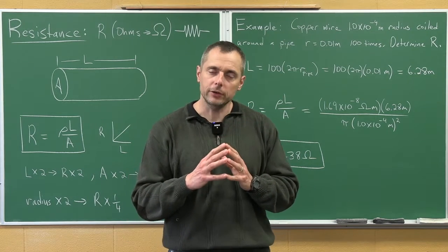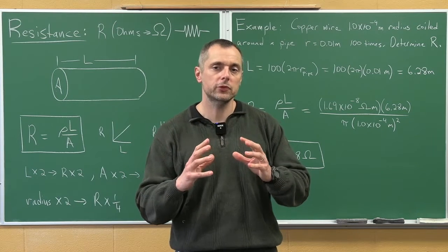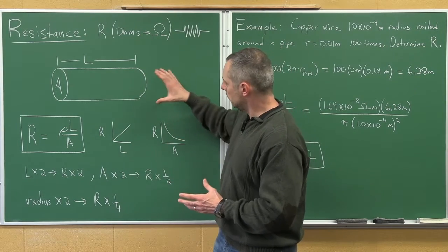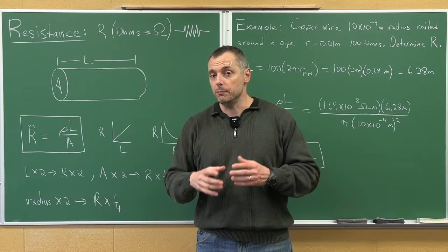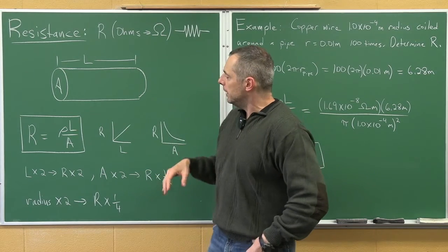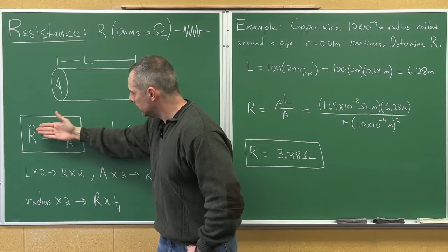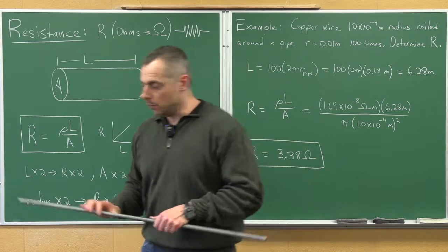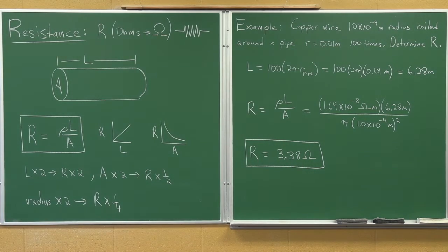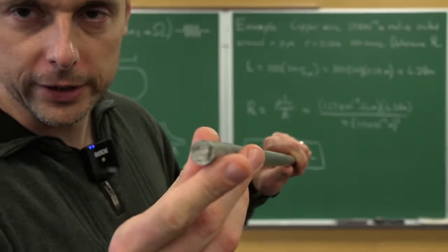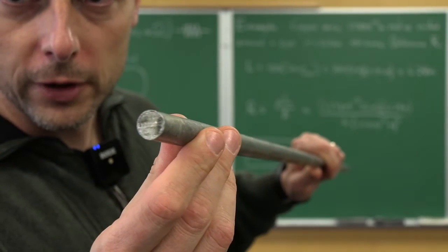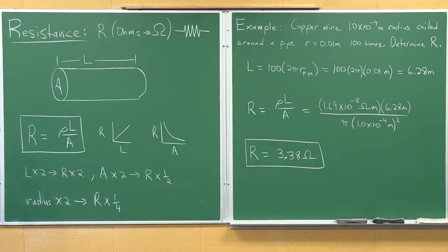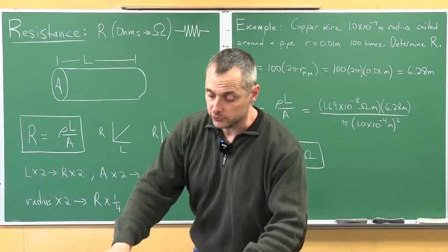So we can actually calculate the resistance, the ohms of a given conductor. And here's the formula, but basically, first of all, conductors usually are made like long cylinders. But it doesn't matter the shape. If you cut the wire, it could be a square wire, and you look at the end, it'll most likely look like a circle, like this right here, right? So there's a circle. So that area, pi r squared of this, is what I'm talking about here. And then, of course, it's got a certain length. All these must be in meters.